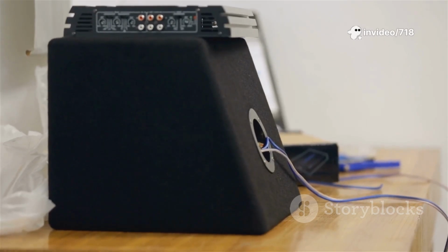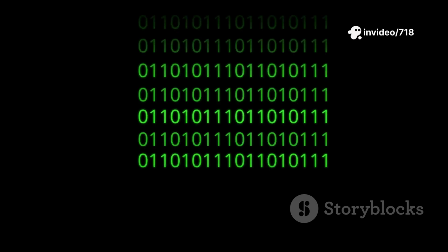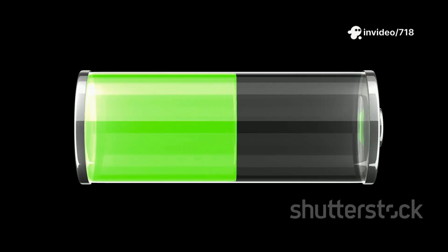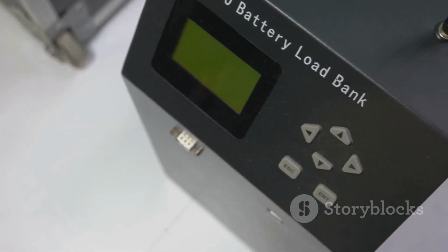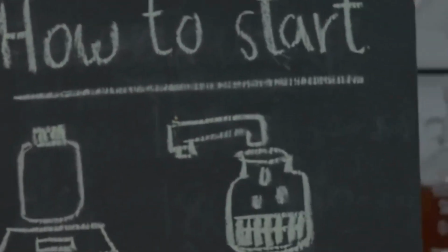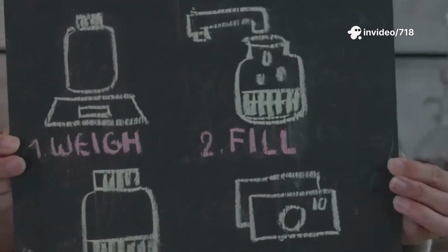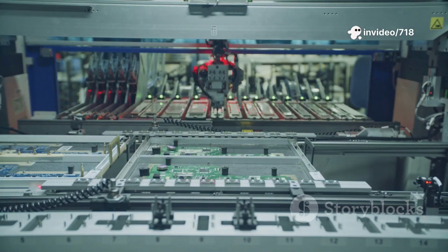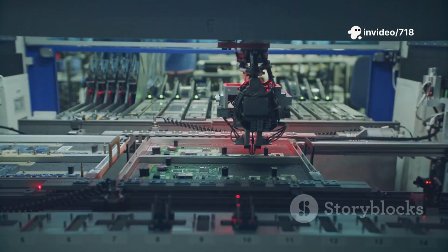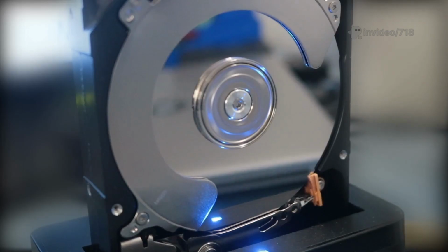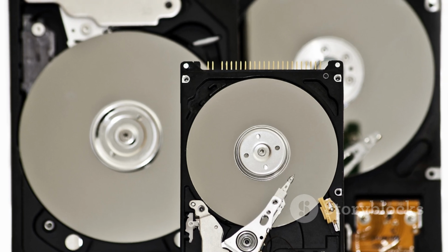The sense amplifier now acts as a driver. If it detected a 1, it uses its own power to fully recharge the capacitor. If it detected a 0, it ensures the capacitor is completely drained. This entire cycle, pre-charge, row activation, sense and restore, happens automatically every single time a read operation is performed. It's a seamless two-step ballet: read, then immediately rewrite. This ensures that the data is preserved, ready for the next time it's needed.